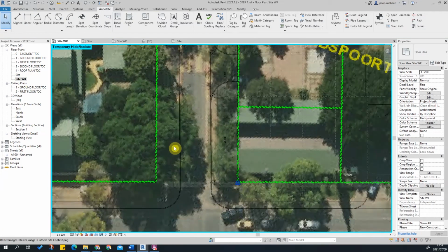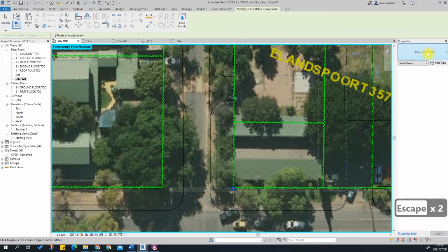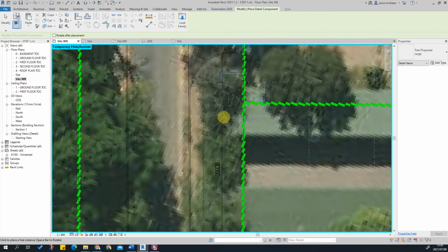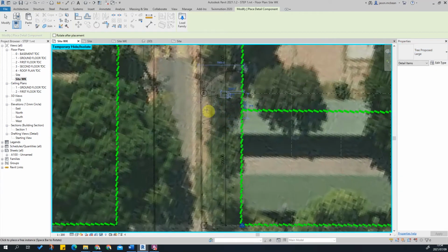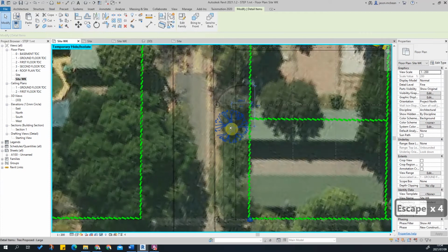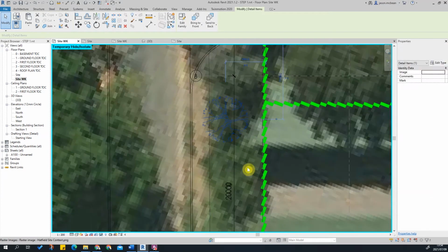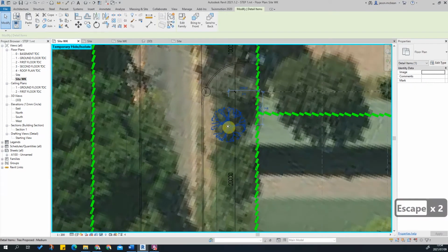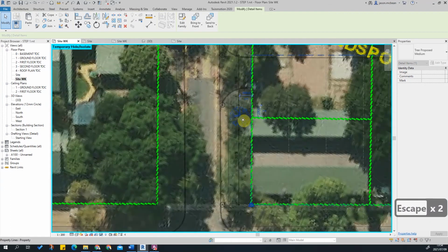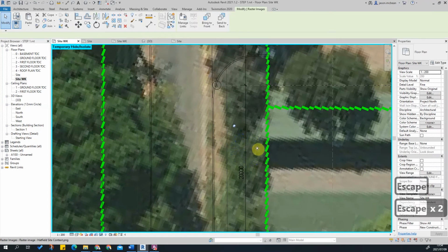And we're going to have some proposed trees. So here we're just going to go back to component, and here we're going to go to proposed. Proposed trees work slightly different. Here we have to work with small, medium, and large. So here I'm just going to use 2 medium trees along here because I don't want these to be really big trees. I might put some new trees along here, medium, because I'm going to do some additional work here. We haven't started with the materiality yet, so we'll get to that in a minute. But here I can use maybe 2 of these. Let's grab that.